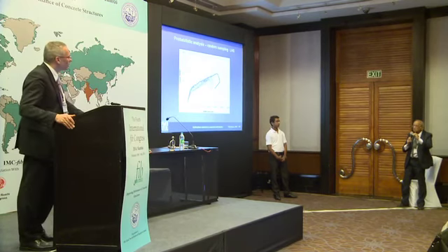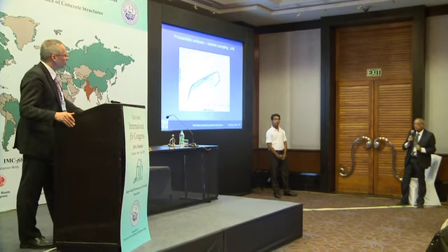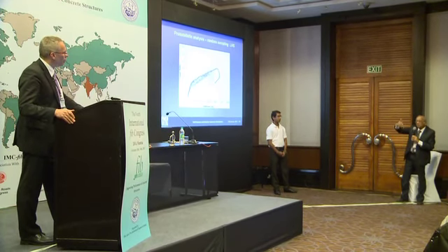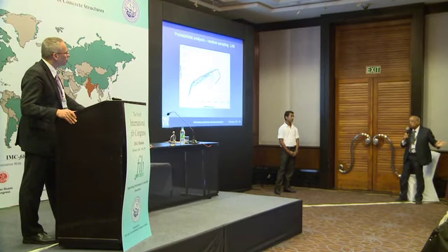Sir, in the old days, the greatest challenge was to choose the right kind of element to describe your structure. And I have known plate and shell element structures, deep structures, being modeled with the wrong element and coming to totally wrong results. Yeah, that's always the danger when using finite element analysis. This danger doesn't matter if you are using linear or nonlinear. This problem is always there that somebody is using wrong elements.